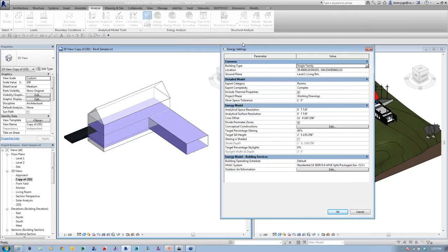And this is really the heart of the whole project and process. We have the building type in here, and inside the building type we have all the different options. This is a single-family home, but there are museums, hotels, motels, dormitories, all this other stuff. And what happens when doing this? This is going to enact some kind of performance within the building: the operating schedule, how many occupants are expected per floor area, and what kind of heat is generated in there. So a library has a certain amount of storage and people involved in the different hours of operation.